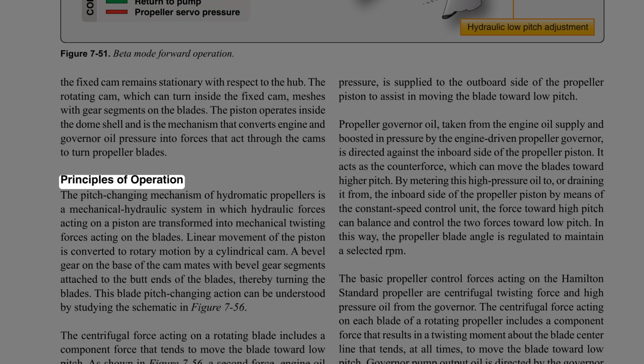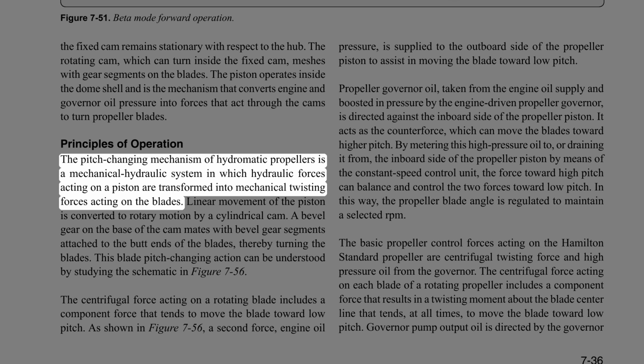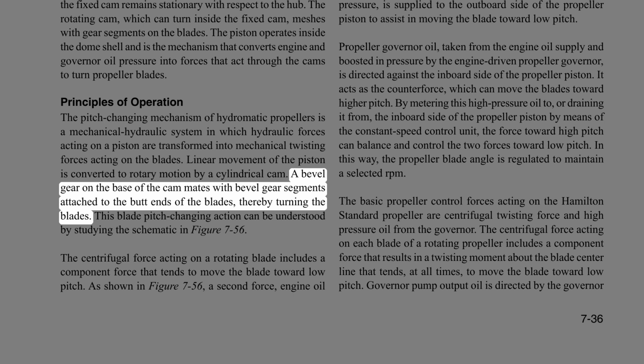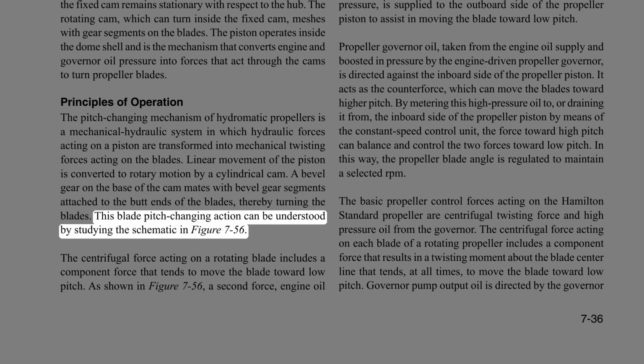Principles of operation. The pitch-changing mechanism of hydromatic propellers is a mechanical hydraulic system in which hydraulic forces acting on a piston are transformed into mechanical twisting forces acting on the blades. Linear movement of the piston is converted to rotary motion by a cylindrical cam. A bevel gear on the base of the cam mates with bevel gear segments attached to the butt ends of the blades, thereby turning the blades. This blade pitch changing action can be understood by studying the schematic in Figure 7-56.